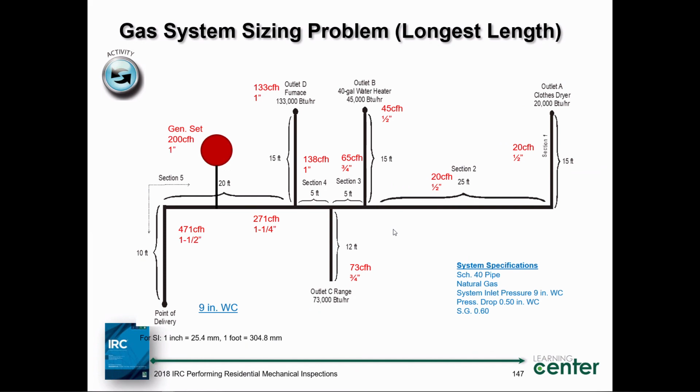Correct. Now I'm going to mention something here that's not even in the code. But if you're a contractor, if you're an installer, you understand this. Gas meters have capacities, ladies and gentlemen. Normally a house meter's like 250 cubic feet per hour, 200, maybe some 300. Then you have a huge jump. Maybe it goes to 500 cubic feet per hour and 900.